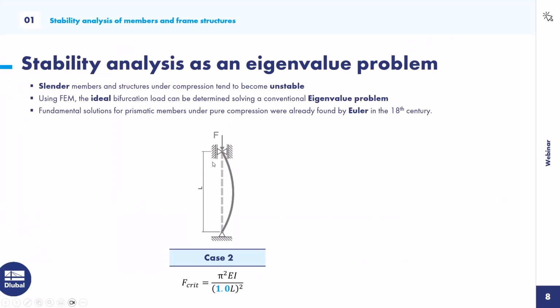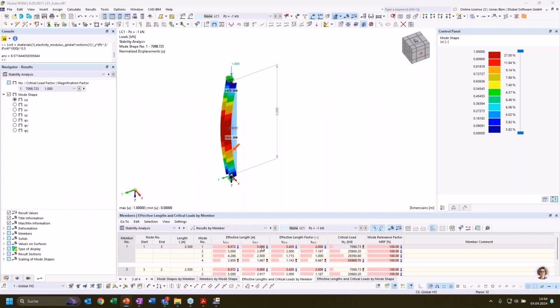look at the formula for the calculation of our critical buckling length, because the Young's modulus and the moment of inertia have not changed, and also the critical load factor has not changed. The only thing that changed is our reference length L for the member. It's divided in half, and that is then only visible in the buckling length coefficient, which is now 2 instead of 1 for each of the members. So we could still use this effective length factor for the stability design within steel design, or some design add-on. It would still be valid.